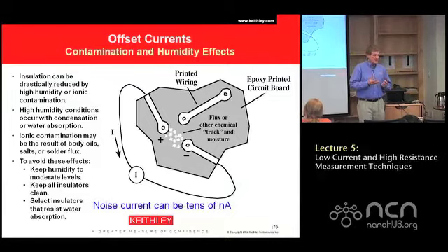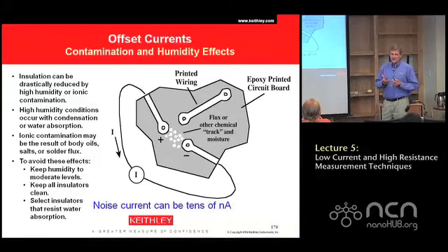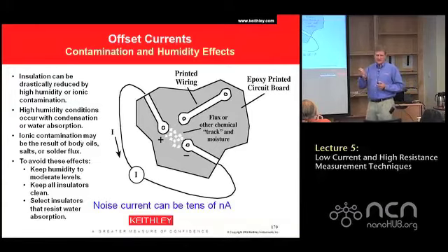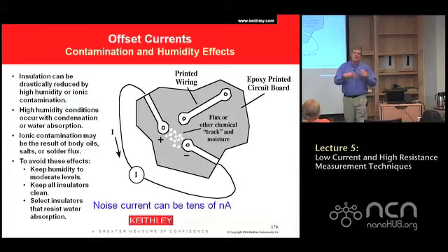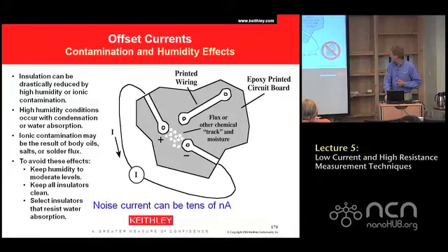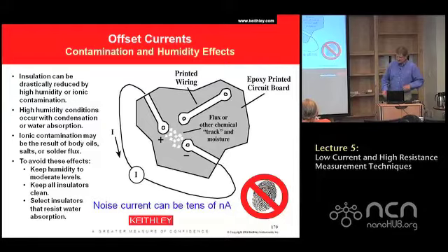You usually have direct control of the humidity, and you can keep it low. The other thing I see people frequently do, they just stand there and they'll fiddle with a cable, and they'll flip around the cable and they'll finger the end of the cable. You get your fingerprints on cable Teflon insulators and you've contaminated that insulator. And it's very hard to clean it up again. The same with probe needles and things like that. So you really don't want to touch anything that you're going to try and get low current measurements out of. Oop, no fingerprints.